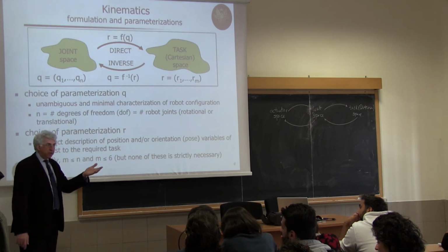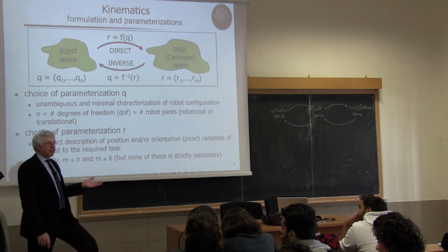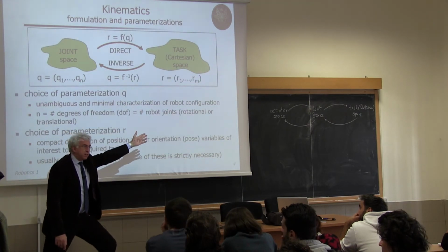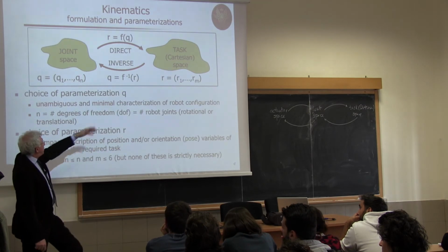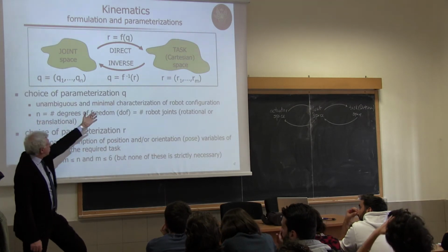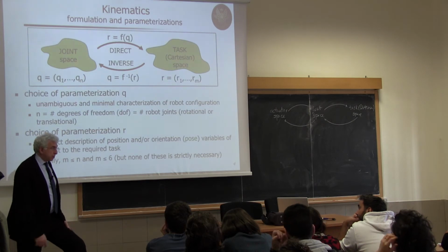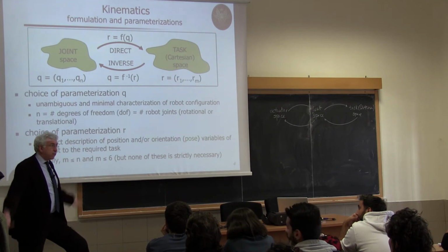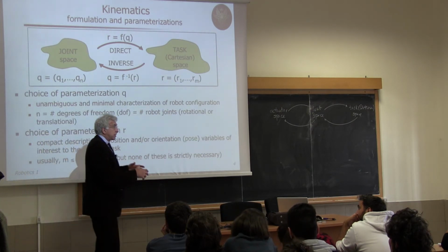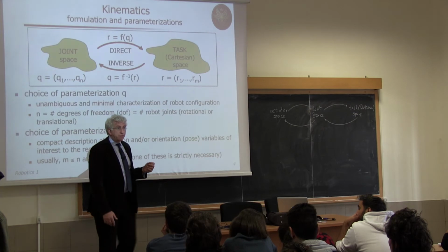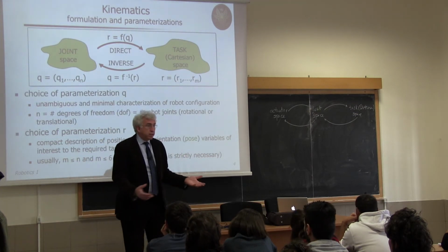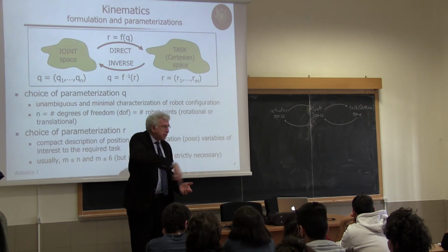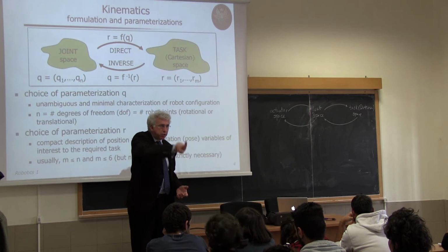In fact, we reasoned about this with the example of the SCARA, where we said we have 6 variables desired for the task space, and we have 4 variables to find that solve this inverse function. And there is no inverse function well defined everywhere. And even where it's defined, even if we confine ourselves to orientations of the end effector of the SCARA which are compatible with the mobility of the SCARA, so the end effector can always point in one direction, but can never go there or there.